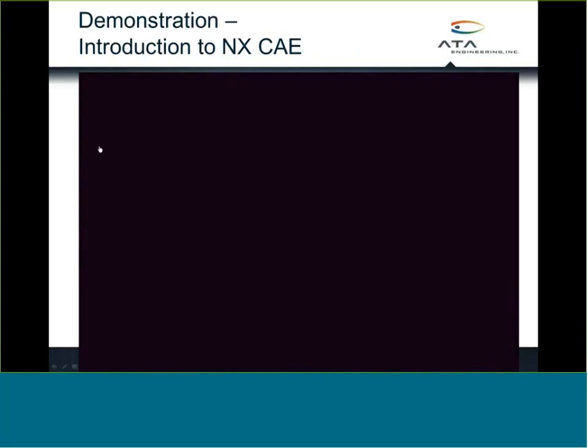Okay, having said all that, I'm going to dive into our first demonstration here. For this demo, we're going to look at a static analysis of an enclosure for a piece of electronics hardware. What we're looking at here is actually half of the enclosure, and we want to analyze the stresses right in the vicinity of these bosses due to the load created by the snap fit process of the mating half of this enclosure.